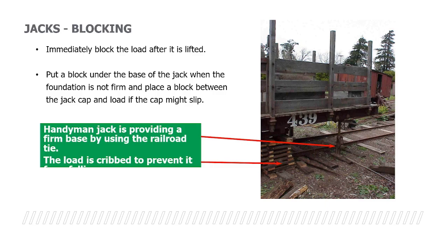So once again, find some type of hard surface or hard type of material that you can lay directly on that soft surface. And then from that point forward, you can actually start jacking up whatever you're trying to do at that time. But once again, look at how much capacity that jack has in order to lift any type of an object. It's going to be marked on the jack itself.